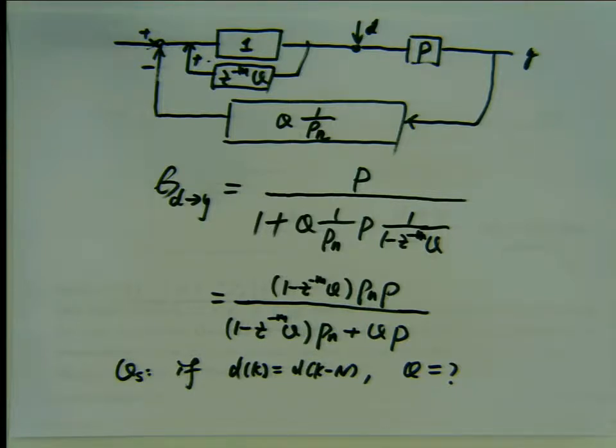So one thing you can take a look at is the earlier result. What is the internal model of the periodic disturbance? More specifically, what is A_D? We mentioned D for the disturbance. What is something A_D times d_k that will go to 0?